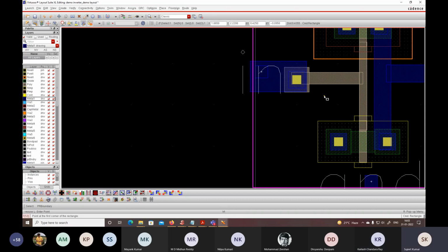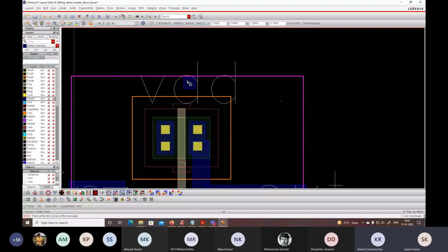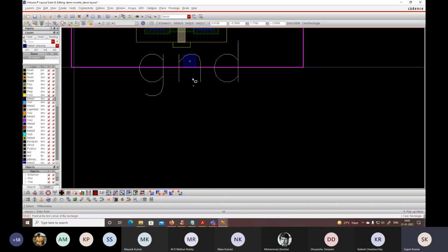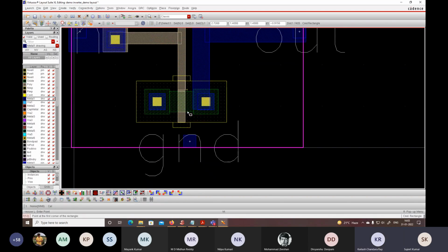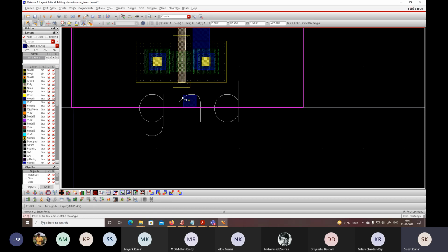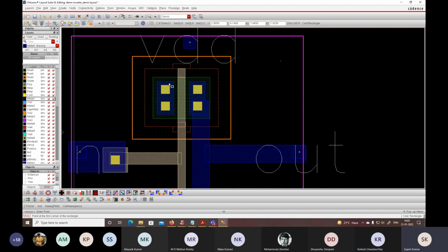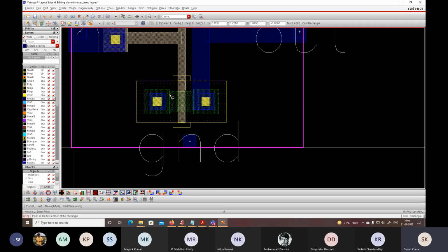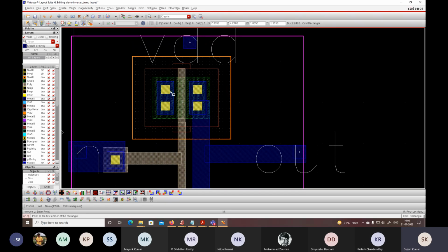Okay sir. So now we are going to connect our VDD and ground. So our VDD is of layer metal 1. We are going to connect VDD and ground for each metal 1 layer here. Also, our substrate is not here, because in the circuit we have used the body. So the body is not available here, so we have to invoke the body of this too.